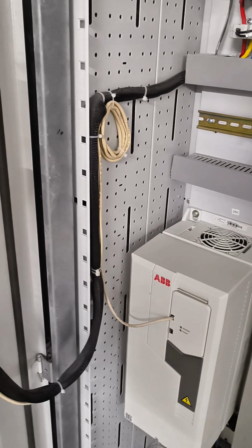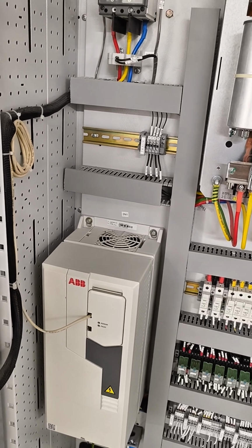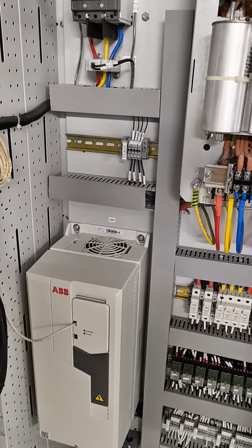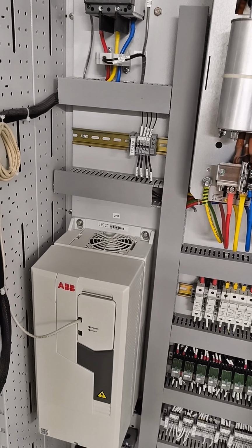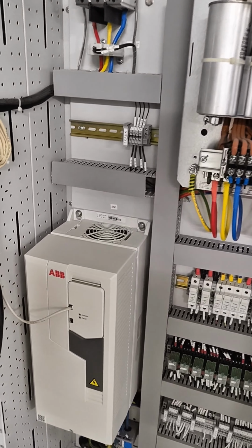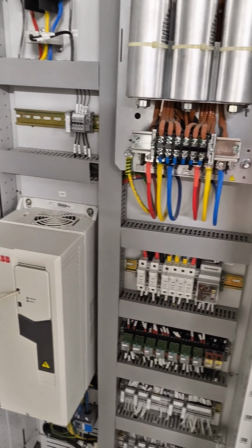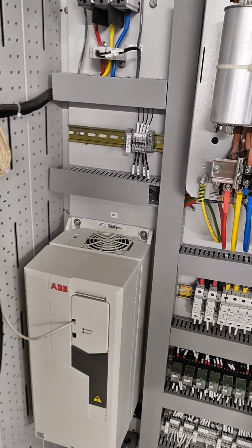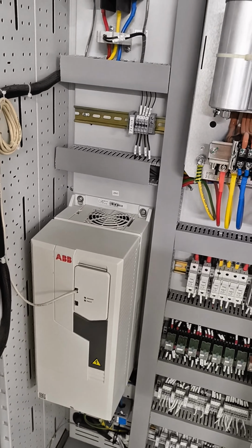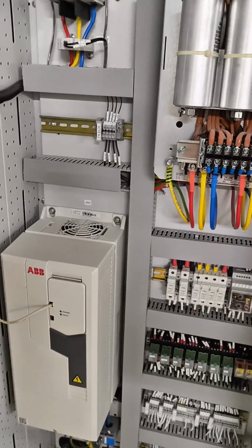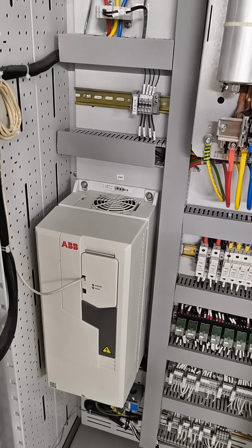Now we will discuss why it's mandatory to monitor run hours. Monitoring run hours is crucial for maintenance planning. Every piece of equipment, like our motor, gearbox, whatever we are using in our industries, requires maintenance at specific intervals, whether mechanical or electrical. Suppose our motor's bearing requires lubrication after running 2000 hours. If we don't know how long exactly our motor has run, and do not have appropriate running hours data, how could we proceed with lubrication?